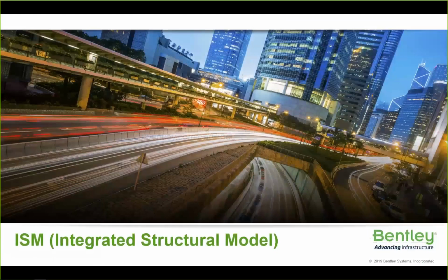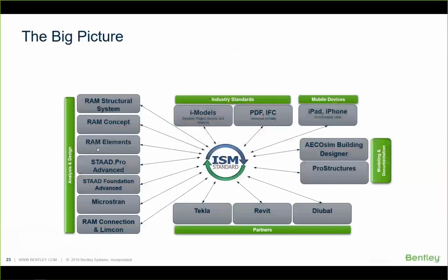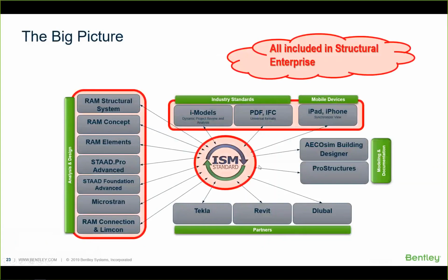Next, let's come to the ISM. ISM stands for Integrated Structural Model. In Structural Enterprise, there are many programs available. You can communicate to all these programs through this ISM workflow, as well as to other programs like Bentley, Ecosim Building Designer, ProStructures, or Autodesk Revit or Tekla, which also has an ISM plugin. Using which, ISM models can be imported as well as exported to all this software. And all these programs highlighted in red are included in Structural Enterprise. So that is the big picture.